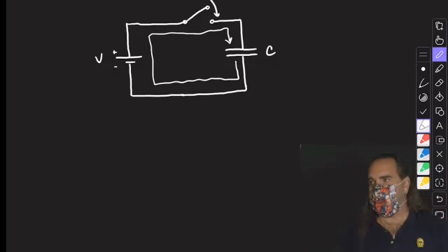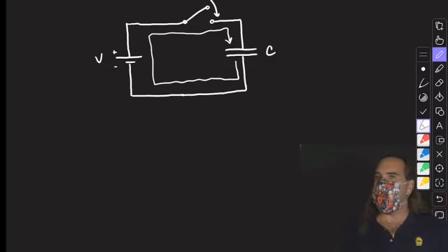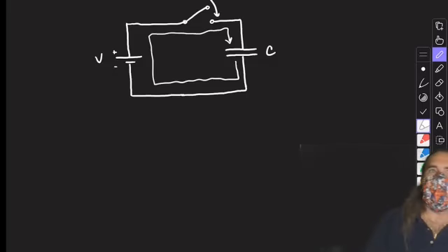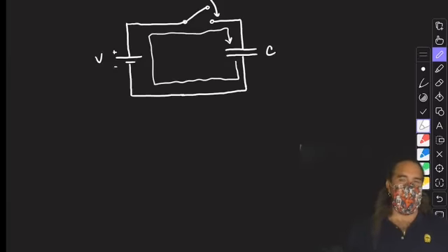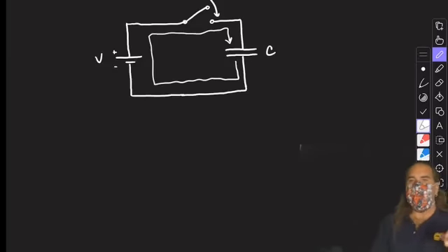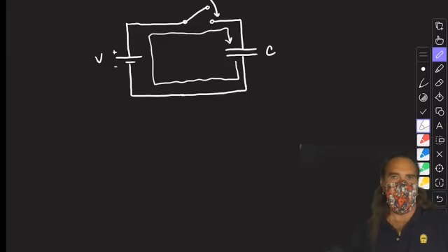Now, generally, the rise time is influenced by the size of the capacitor. You can imagine that the bigger the capacitor is, the longer it would take for that capacitor to fill with charge, just like a bucket. But other things that influence the rise time is how much resistance there is to the flow of electricity in our circuit. Now, this circuit has no obvious resistor, but there are wires here.